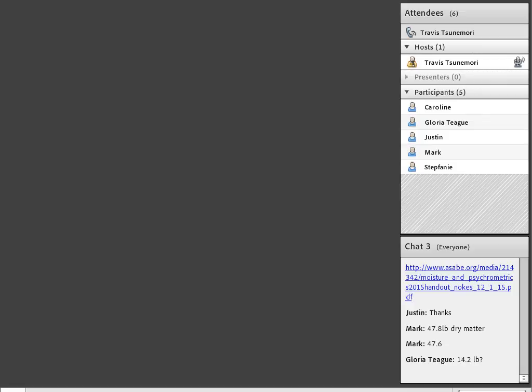Okay, so if you have your psych chart, it's time to pull it out. We're going to review this real quickly. We're going to put all these things back together when we get to the grain drying problem. So if you know two properties of an air-water vapor mixture, then you know all values. This is the great thing about the psychrometric chart: you only have to know two properties, and we can come up with all the properties of the air-water vapor mixture because two properties establish a unique point on the psych chart.